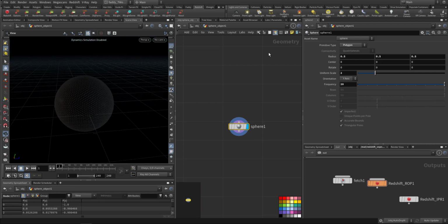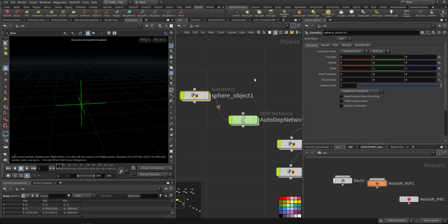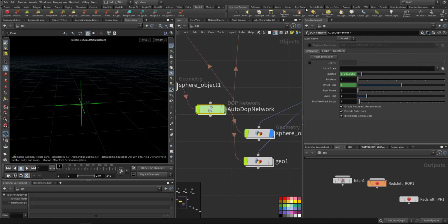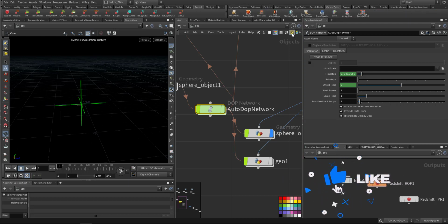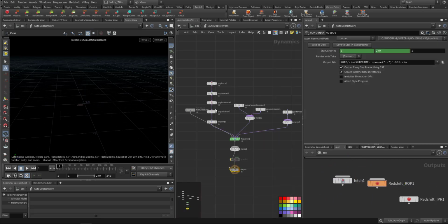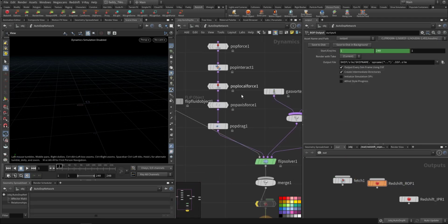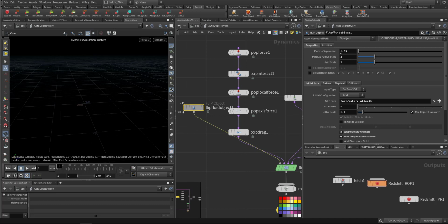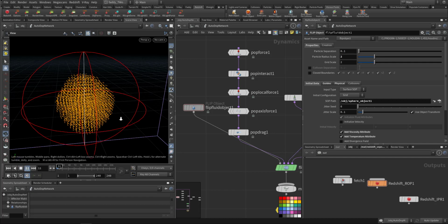and what I did, I went and created a DOP network, and I didn't use the particles. I went and I used the viscosity tab, the viscous fluid. I used lava from object, so I can extract the temperature. So here, let me just go up with the resolution so we can see. So this is the effect. Just give it a second.